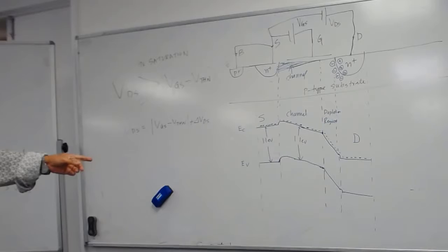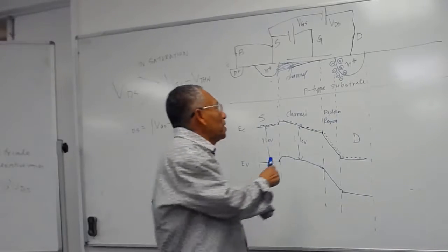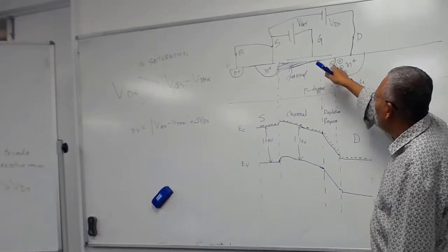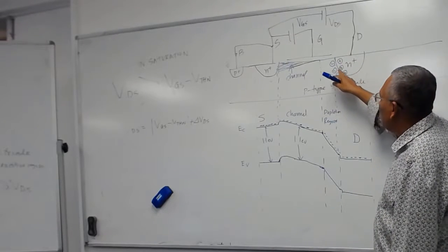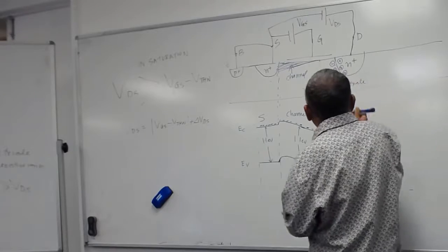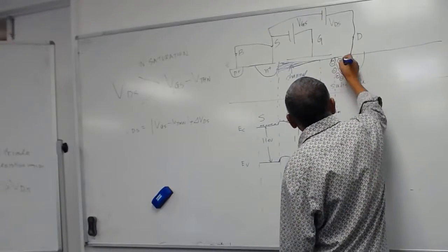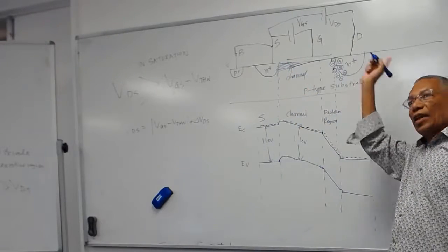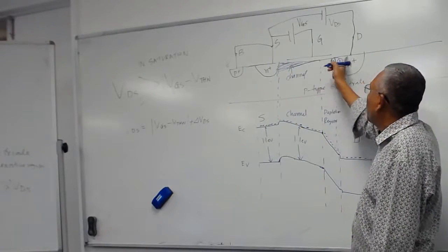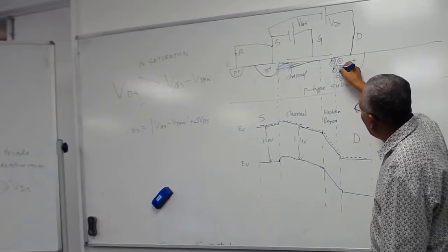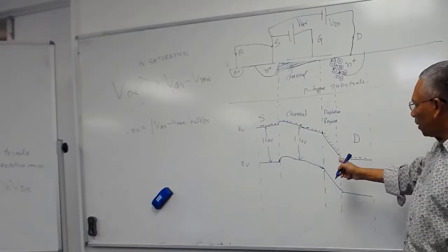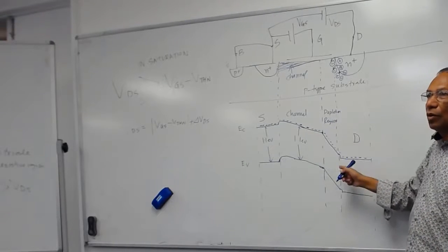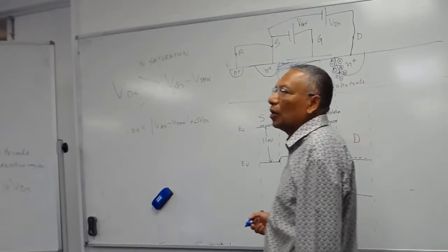I think so, because this diagram makes it very easy. Here you have the positive charge and the negative depletion region, because this is p-type you have negative charge, n-type, positive charge. That creates lines of electric field this way. The direction of the electron is opposite the lines of electric field, so electrons want to go the other way. This is the charge diagram and this is the energy diagram. Electrons want to go down this way, so you have continuous flow of current.